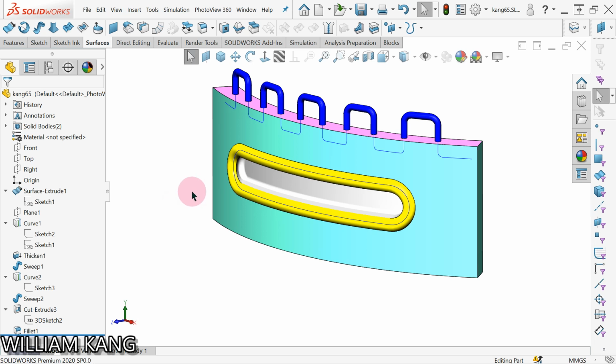I will demonstrate the projected curve command again. Sketch on sketch and sketch on face. The railing is using projected curves, sketch on sketch projection type. Same as the railing you saw on the hull. The sweep is using projected curve, sketch on face, projection type. Same as the window on the hull. The cut extrude is using 3D sketch. Then you use convert entity to get the profile.